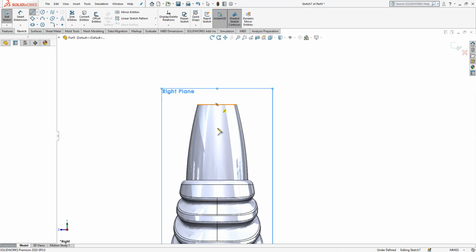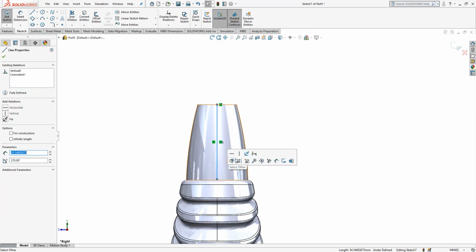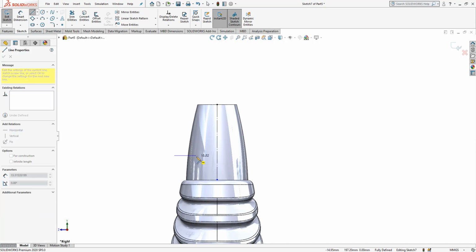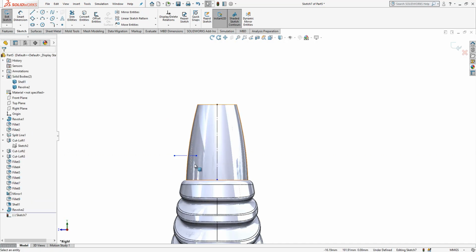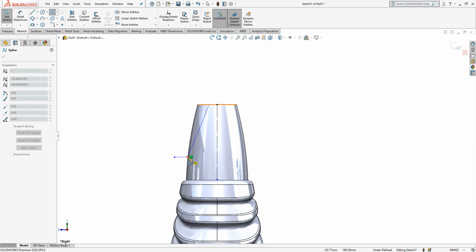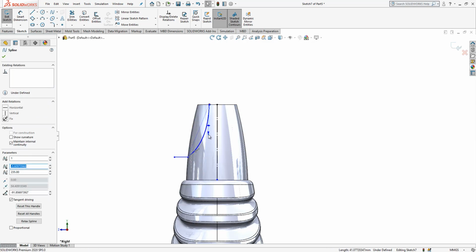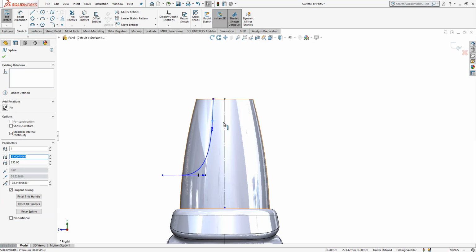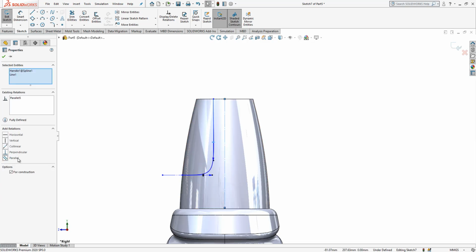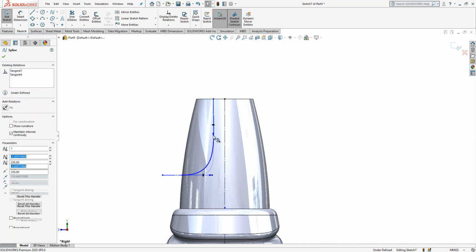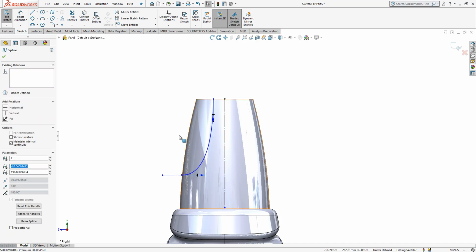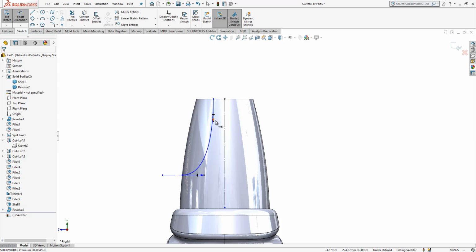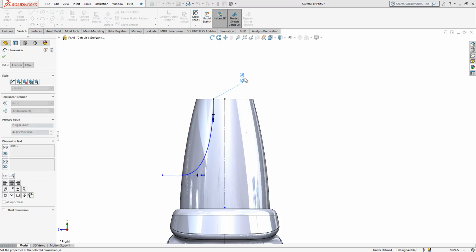And then, as I always do, first create a construction geometry. Here another construction geometry, two lines. Okay, can make it like this. Now spline, 2-point. Why do I use 2-point spline? Because they are easy to handle, guys. If you add one more point, you need to define one more object. So here I'm going to employ parallelism. Okay, let's make it like this. Yeah, I could define here a line and give tangency. That's the same idea, in fact.